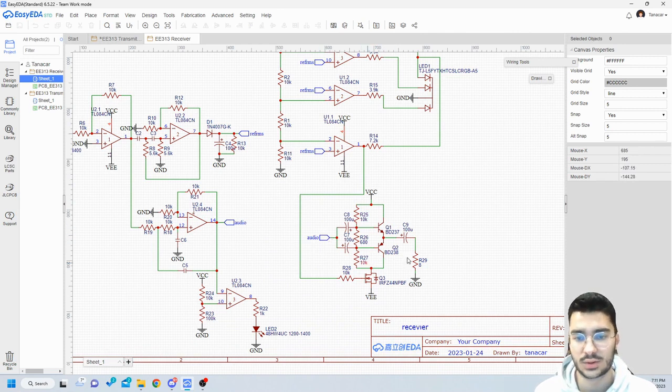We use the class B amplifier design with a calibrated middle resistor for the bias. We have two small signal inputs, and then we generate currents with two complementary BJTs in push-pull configuration, so that we generate a symmetric sine wave AC current passing through the speaker.